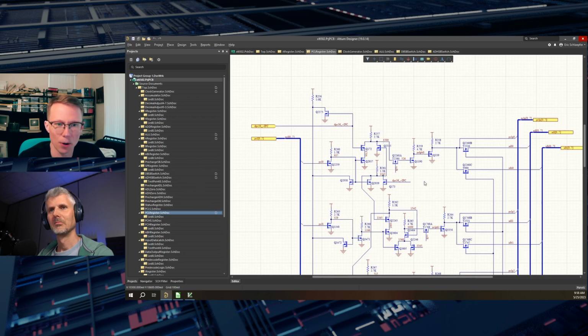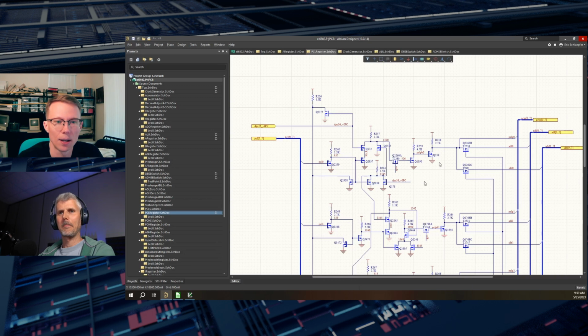And it was also slow, and that has to do with the carrier mobility, I should say. And so that was a problem. But they had been reading papers that discussed using an ion implantation technique to take NMOS transistors and make them depletion mode. And the idea there is that you're shifting the threshold of the MOSFET so that even if the gate to source voltage, I should say gate to substrate voltage, is 0, the MOSFET is still turned on.